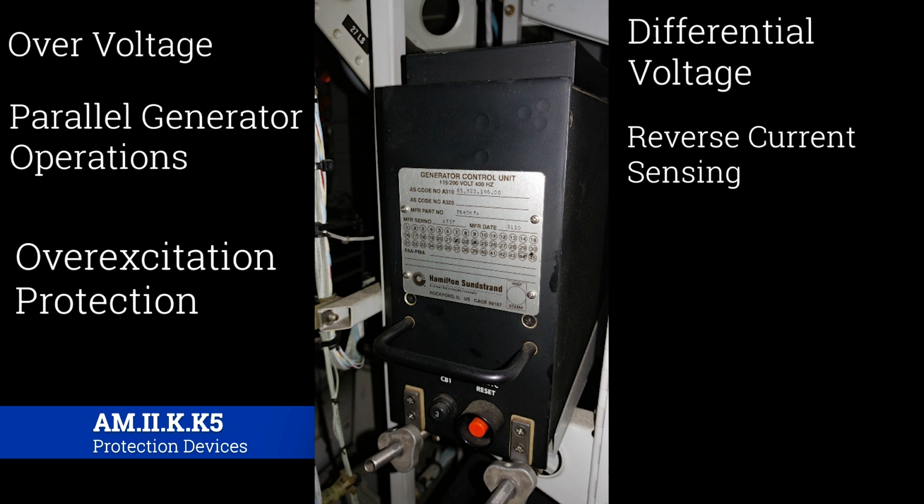But if all of a sudden the generator starts to fail and starts to draw electricity back into it, and the other generators are doing just fine, they're all tied together, and they're producing more electrical pressure than that generator, then that generator effectively becomes a load, and the current will reverse.